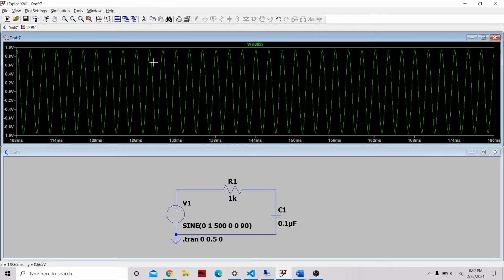And up on this screen, then we can see the output sinusoid. So something you should be noticing here is that we have a signal that is pretty close to the maximum signal here at 1 volt, meaning that we're probably pretty close to the passband, but maybe verging on getting to our cutoff frequency a bit too, since we have a little bit of a drop.